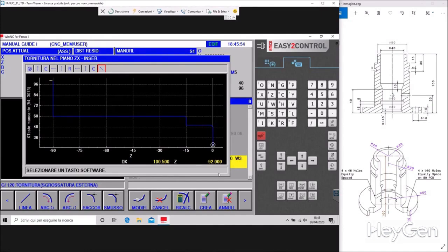Perfect. Now the machine needs something else, because I would have finished. Look at this icon here. It asks me to close the shape, because there are two options for closing it. The shape can be closed this way. Okay, and it would clash with an internal operation, or an external operation. Or it can be closed this way. See, and it fits with an external operation. In short, it's asking me if the selected raw material is connected, meaning it makes sense that we are removing this area. Of course it makes sense.